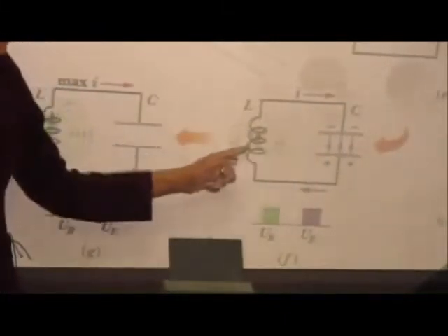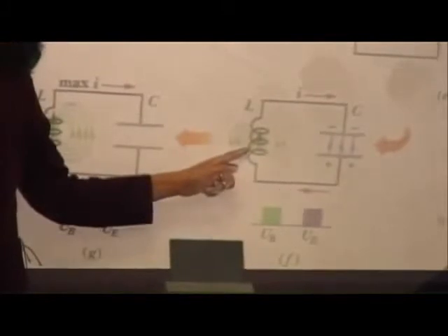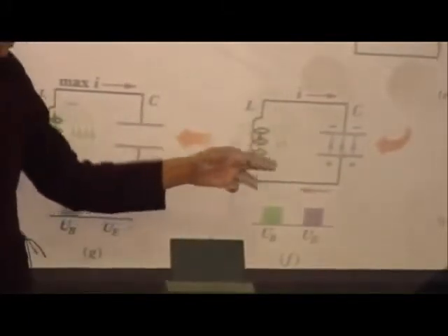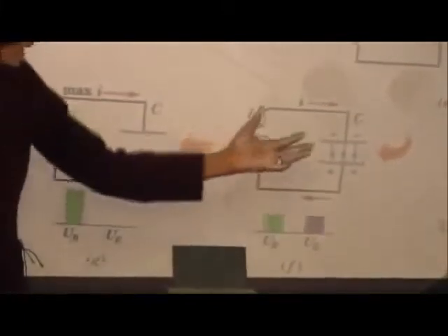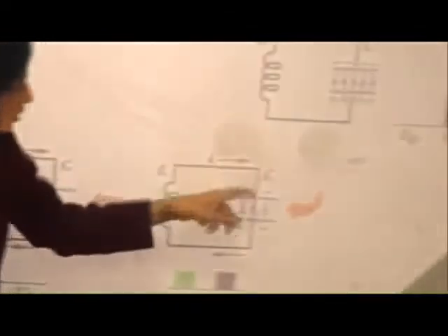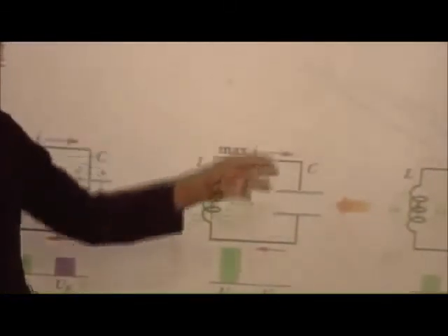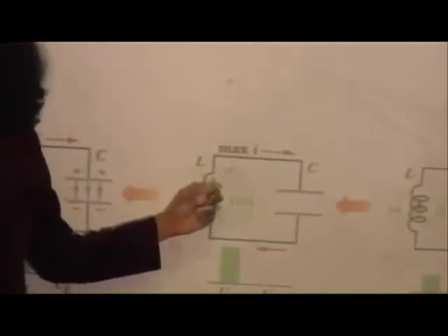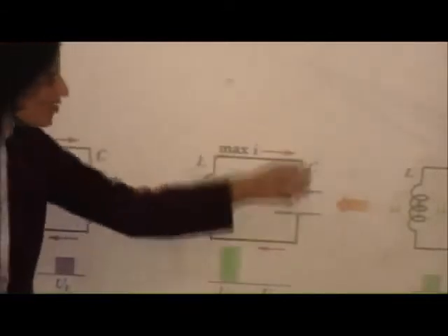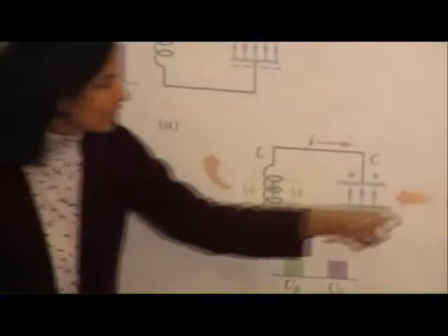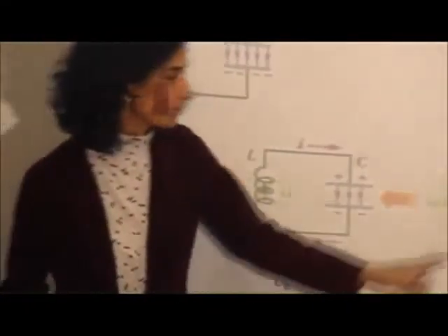At this point, will the inductor again start to oppose? Yes. So the point is that basically the capacitor starts to discharge. Here the capacitor is completely discharged, but the inductor and the current, it says, okay, now the current can go to 0. I cannot do anything, but the inductor wants to maintain it. It wants to keep the current going like this, and if it wants to maintain the current like that, do you see what will happen as a result?